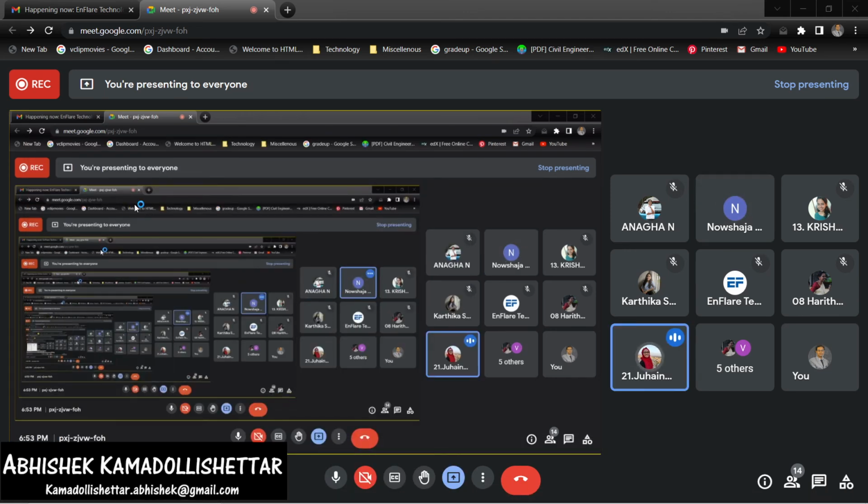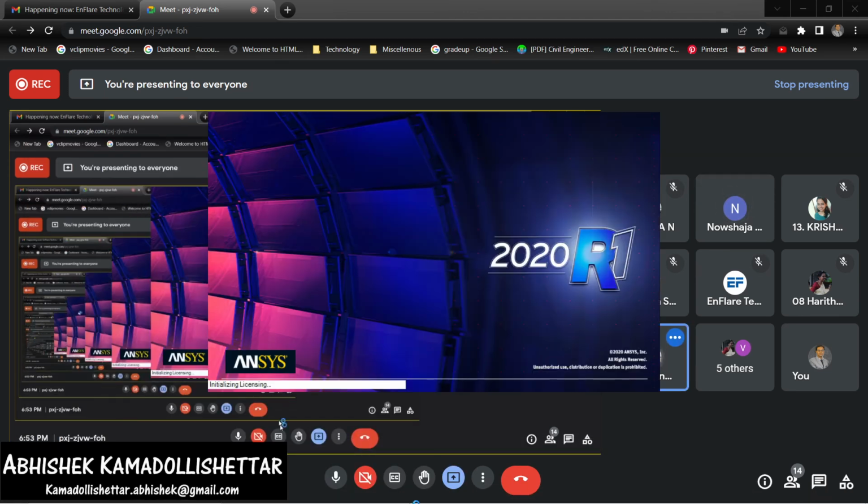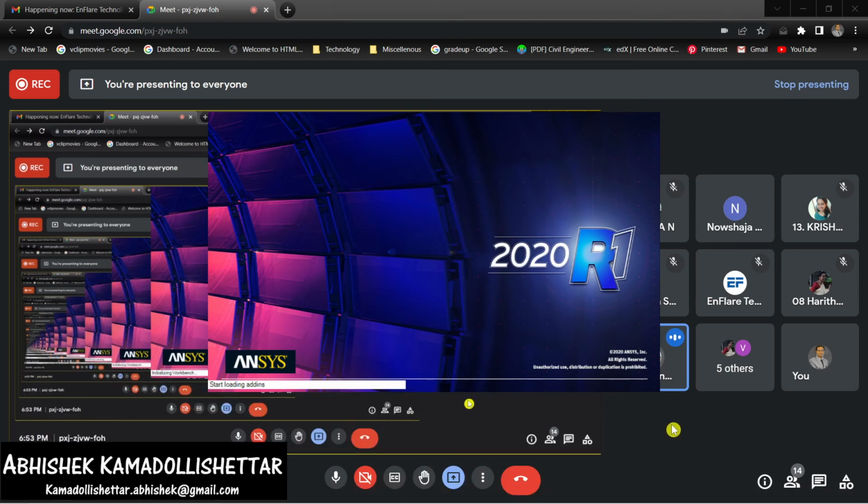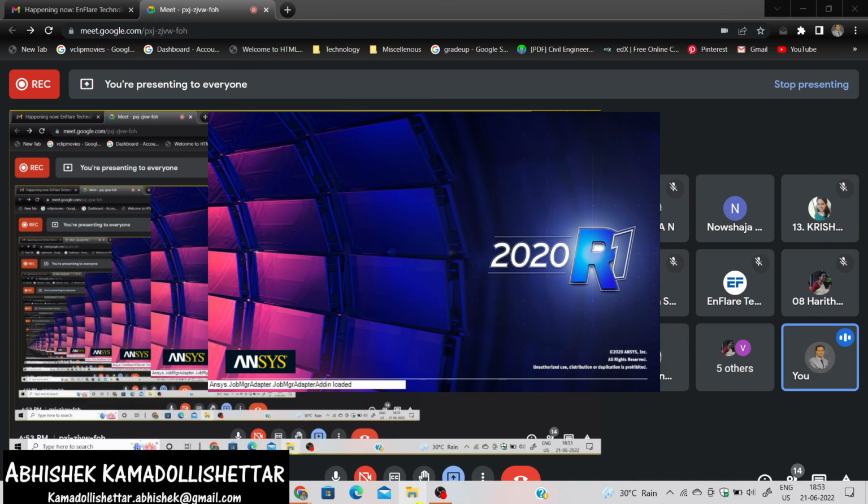Yes, ma'am. Sir, how can we incorporate high performance concrete in material properties? Okay. You need to have some mechanical properties like Young's modulus, Poisson's ratio mainly, and ultimate compressive strength and tensile strength.